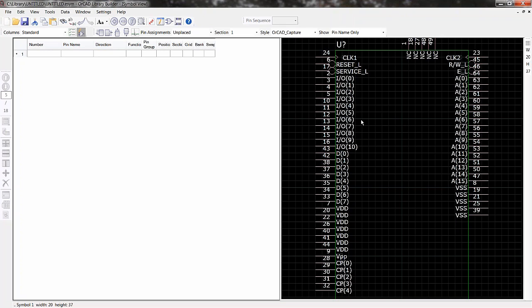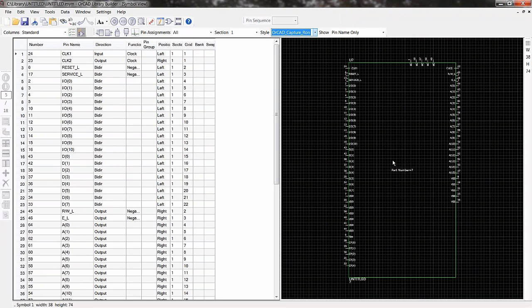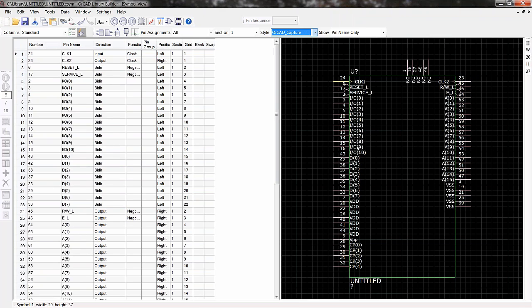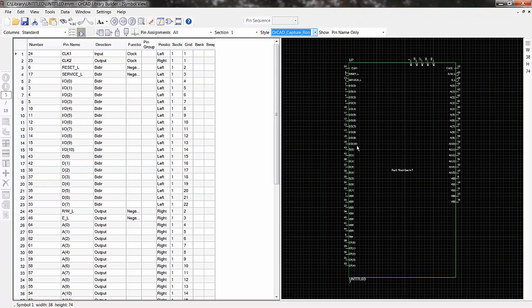So as you build templates, you can save the template to your own name. So here I have a couple different names, and if I select one of these, let's see what my other symbol looks like. So now I have, in this example, pins. Oops, I'm changing that. In this example, I have only 1/10 long. We call them pin whiskers or pin lengths, and my pins are on 2/10 spacing. So this doesn't look very nice. I like the OrCAD one better. So you can change and create your own template styles and then apply those here.